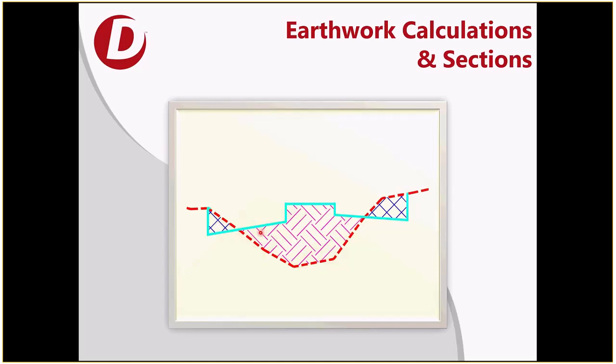And you can say, we're done. You just let Civil 3D do its stuff, and that's our earthwork volume. But there's a number of things that you really need to be careful when you're generating volumes and building the model, that you accurately are depicting both the subgrade line and the existing ground line to make sure the earthwork is accurate.